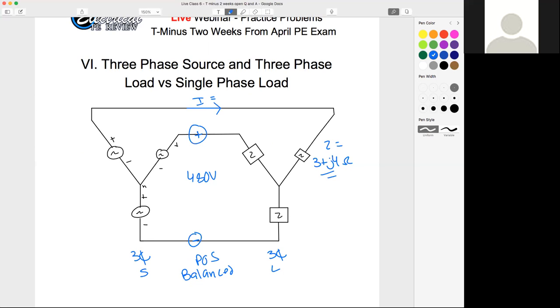All right, so Arb said I line equals I phase. Kahina said 480 divided by the square root of 3. Great, Kahina, that's what I was looking for. So Craig and Bernie, you said V over Z. Did you mean 480 volts, or did you mean something else? Tony said V to N over Z. Great, Tony, fantastic. Arturo said I'm too slow. Mary, great, 480 divided by the square root of 3 times Z. Fantastic. Shamil, fantastic. Bo said, I agree with John. Great.